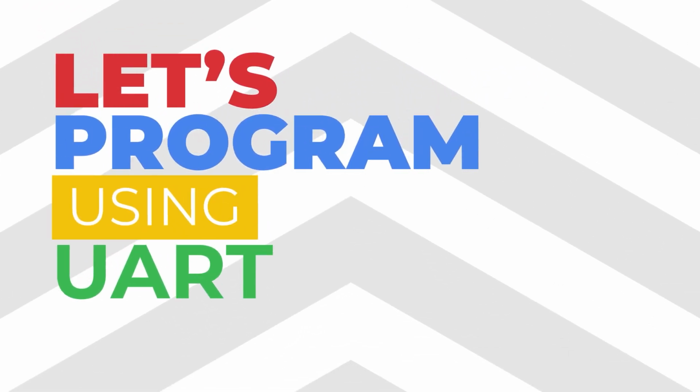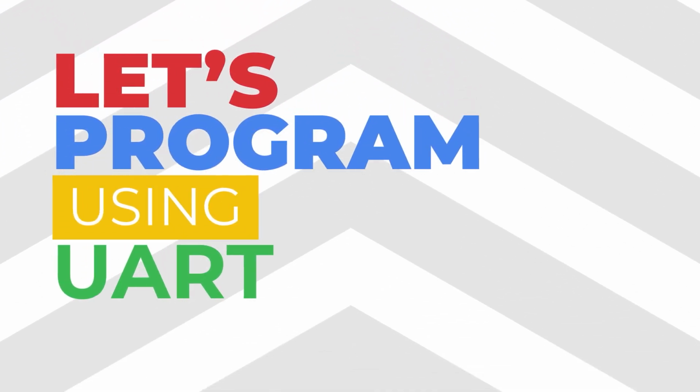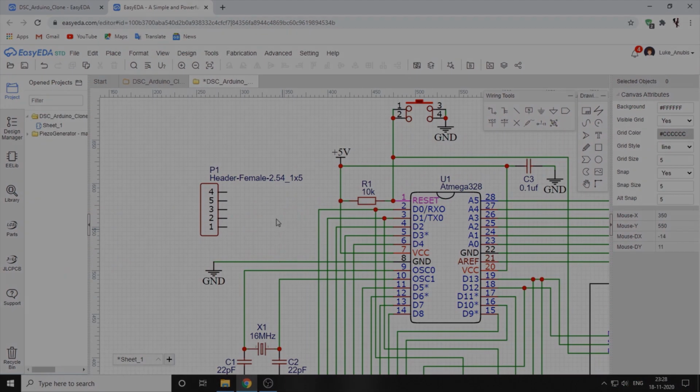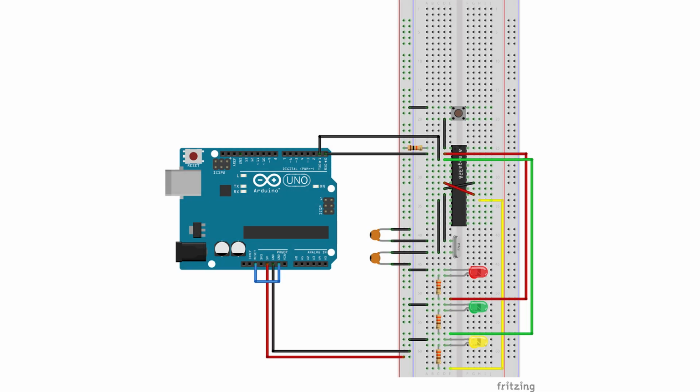Now, there is also another programming mode known as UART, aka Universal Asynchronous Receiver Transmitter. This only uses two wires to transfer and receive the data serially without requiring any clock pulse like SPI. We can also furnish with the programmer a handshake signal to the reset pin of the target to automate the programming process. Otherwise, we would have to reset the target IC manually just before you begin the program.